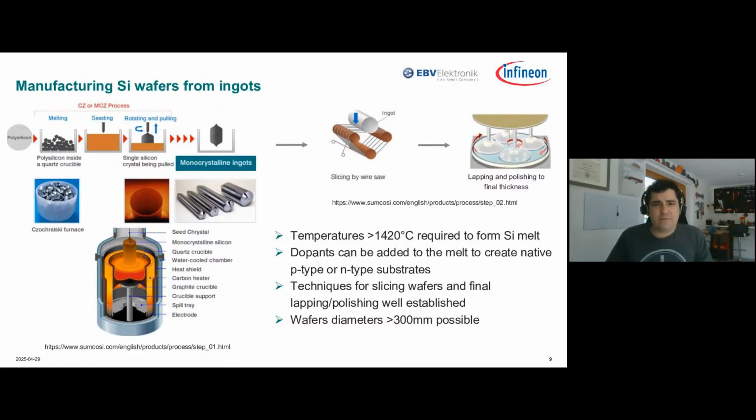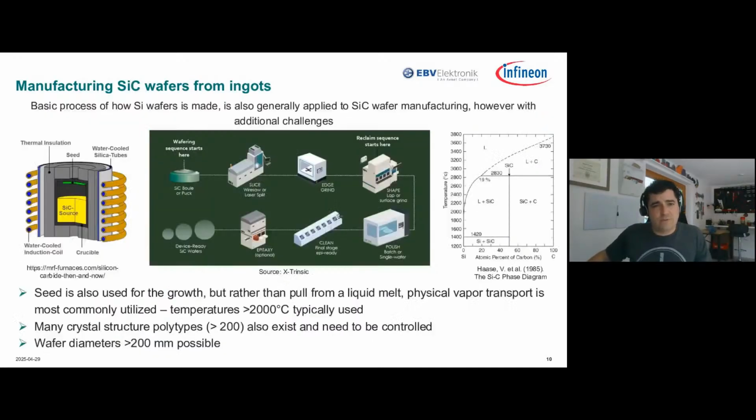If you remember back from your university days, usually this is compared to making candlesticks, where you dip the string into the wax and you rotate the string, and gradually this molten silicon layers upon itself, and you have this very high quality intrinsic silicon wafer, or doped N+ silicon wafer, or ingot, which is then sliced into wafers.